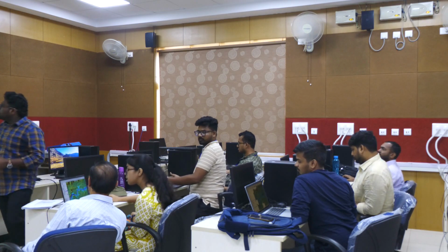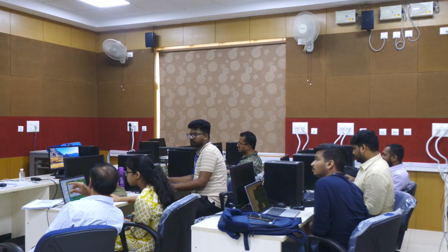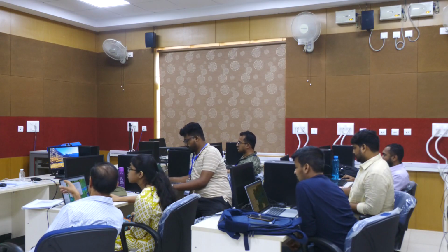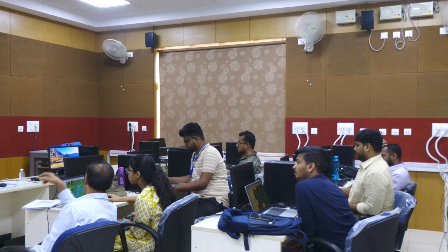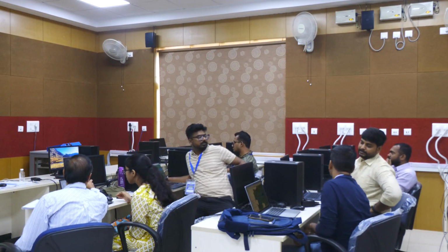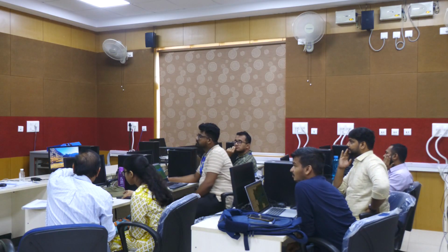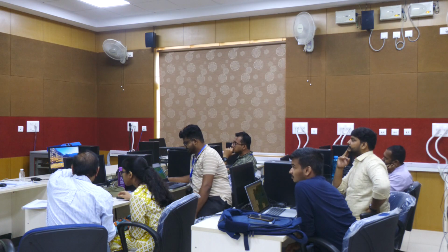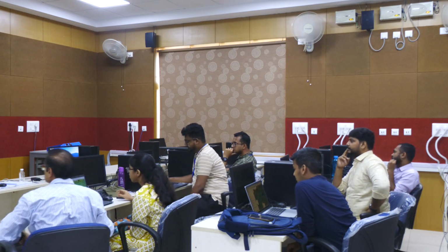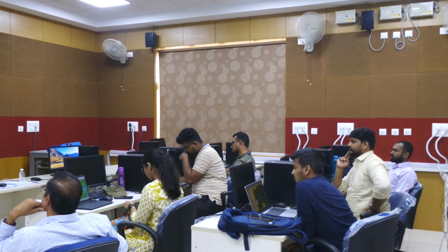Flood inundation. One important observation here, I told you, right, whatever cross section we have drawn, water cannot move beyond that. See here in this case, my cross section is up to here, that's why the flood is shown up to here. If I had drawn up to here, the flood might happen here also. So while drawing cross sections, you should draw long lines, so that it will cover wherever the possibility is there. This is the flood inundation map.